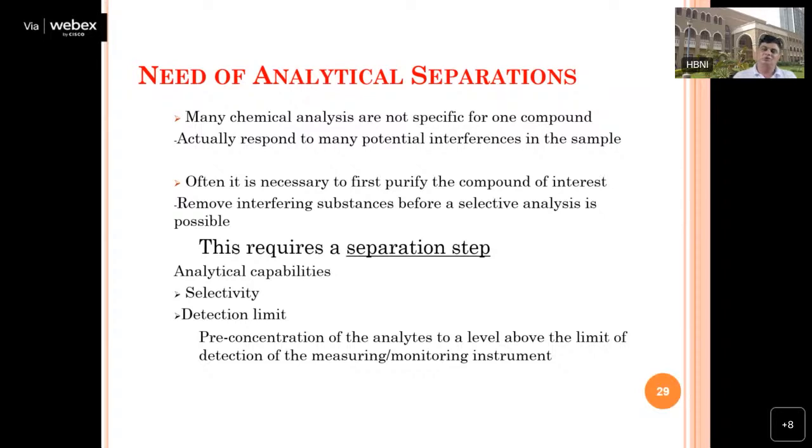The other way is that you look for a selective material. You look for some selective adsorbent which you put into the 10 liters of water, which will selectively adsorb the lead from the 10 liters of water. So these are two ways of doing pre-concentration. One is the conventional way, and the other way you can take the help of chemistry to pre-concentrate your samples.